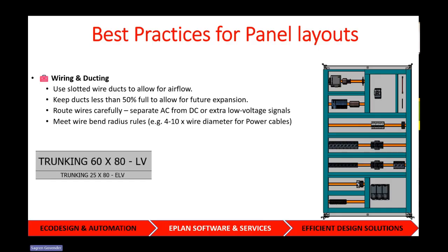Make sure you adhere to the bending radii of your cables, and depending on the power cable, it can range anything from 6 to 10 times, maybe more, depending on the size. So make sure you check that so that you don't bend them too sharply. And what type of cable is it? Finely stranded? Is it stranded? Is it screened cable or armored cable, or whatever the case might be? So just check that out.